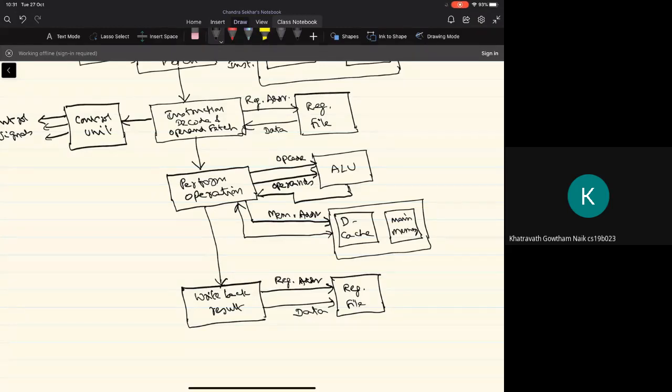So the time taken to complete the operation depends on the value of tau and how many tau it takes to perform the necessary operation using the circuit that you have designed for the arithmetic operation. Now if we assume that all of that can be done within one clock cycle period, then it's fine. Otherwise, we need a mechanism to wait for that operation to complete and then take the result. Again, it is the responsibility of the control unit to monitor whether the specified operation is completed within the clock period or not. Why this constraint of clock period, we will come to that quickly.